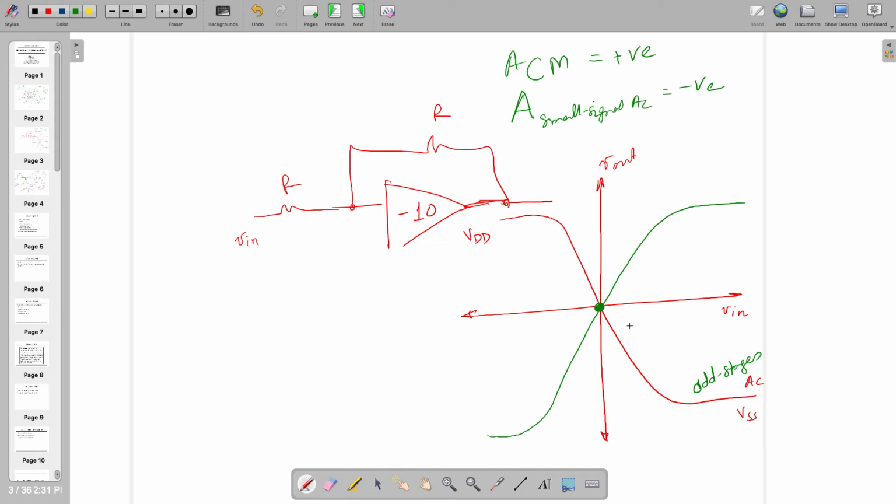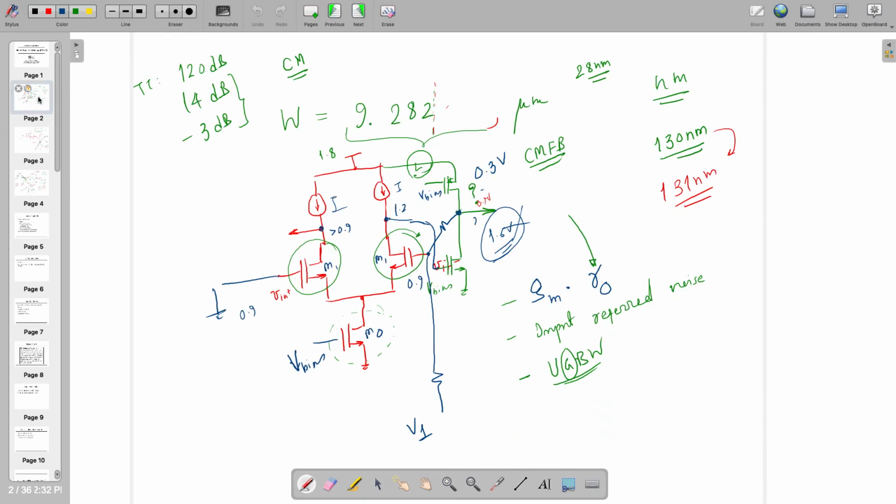But if you have an even number of stages, you may have more stable points. When I'm saying stable points, these are the values where your output will sit. At the output, you may have VDD, you may have VSS, you may have like 0.9 also. At typical corner, you can see 0.9 and you will be happy. But in reality, across process corners, your common mode will be sitting somewhere else. This is happening because, assuming an even number of stages, who is controlling this point?